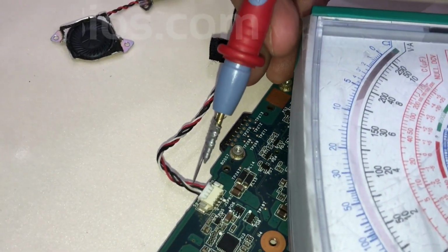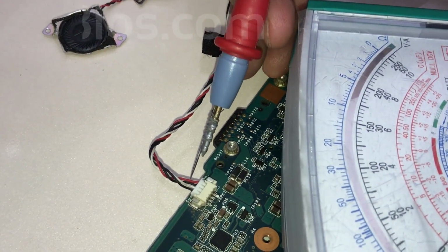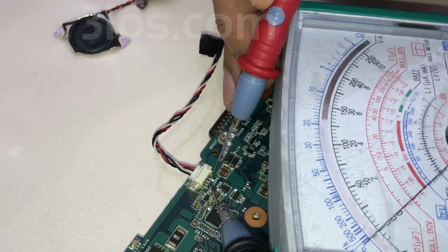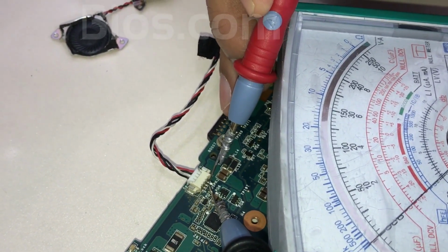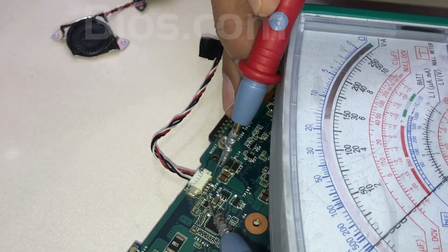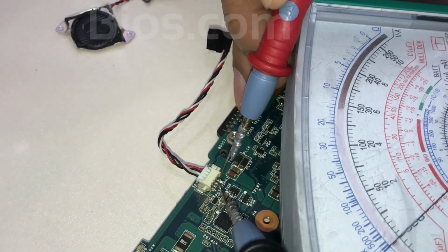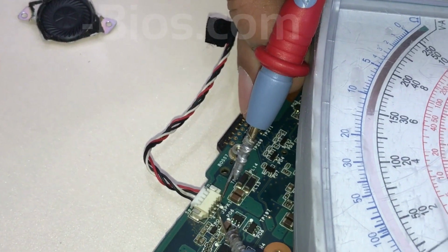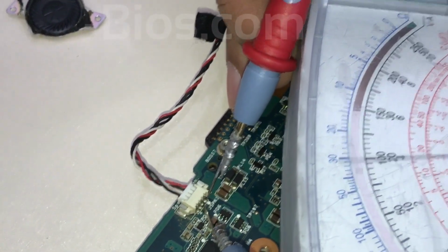Black and white wires are 1 speaker, and the black and red wires are 1 speaker. I place one of the probes on pin 1 or 2 of the speaker, and I connect and disconnect the other probe. A weak noise can be heard from the speaker.